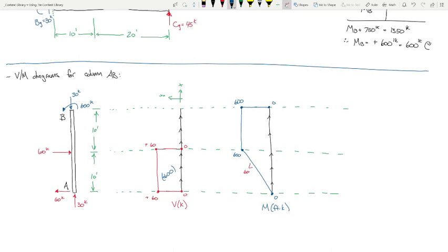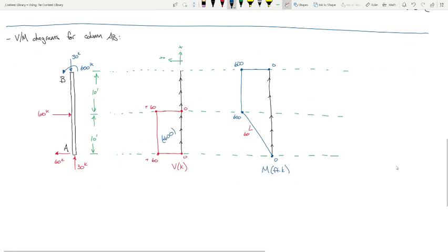That doesn't mean that it's wrong. It's just if you were, as the analyst, expecting it to look like this, and it looks like that, a simple answer would be you flipped your nodes, you drew your joints in the opposite direction. Doesn't mean that the analysis is wrong. It's just plotting it opposite the way you expect it. Okay? Sound good? I just mentioned that to make sure that when you get into software land, you kind of know what it's doing. Okay. And again, that's the weird one.